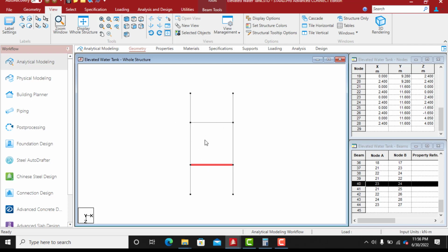The tank is going to be directly in contact with the grillage beam. Then from the grillage beam, the load will be transferred to the main beam, and from the main beam to the column. So this grillage beam has a cantilever extension of 1 meter.